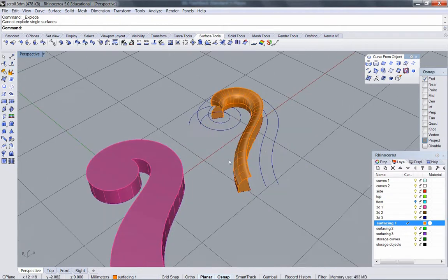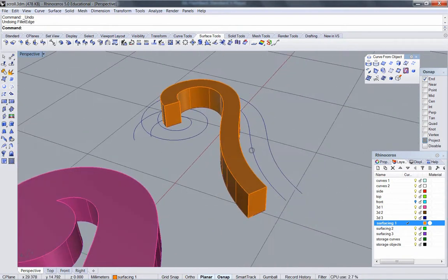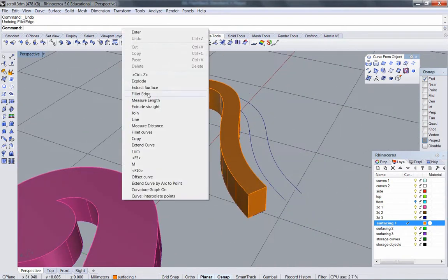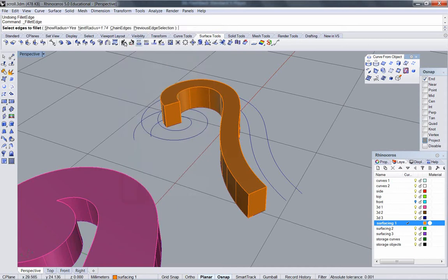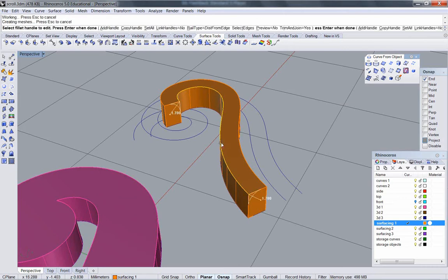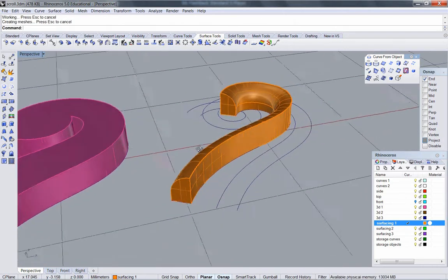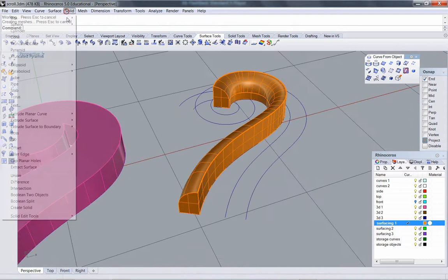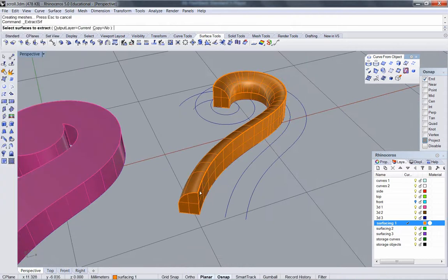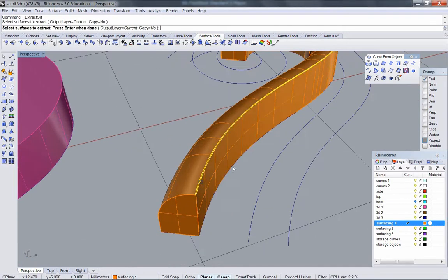Now if I wanted to avoid that, and it would be smart of me to avoid that situation, I could fillet it just a little smaller than 1.74. I'll make it 1.7. Okay. That way, it's clear that there's this little extra surface here all the way along.